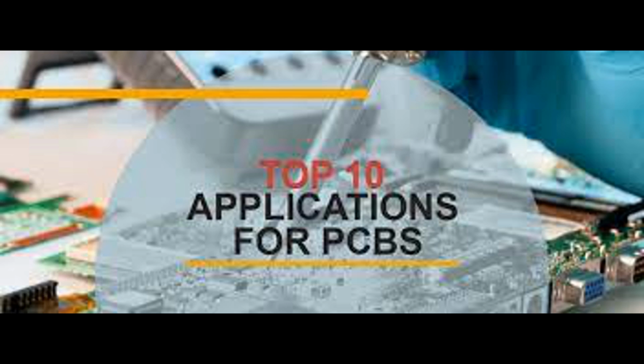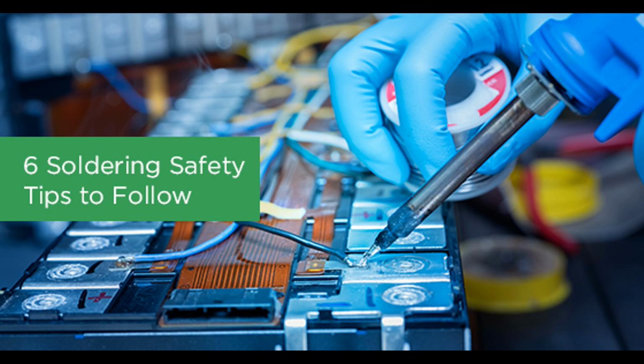The design and manufacturing of PCBs involve specialized software for schematic design and layout, followed by the fabrication process, which includes etching copper traces, drilling holes for vias, and applying protective layers. After fabrication, electronic components are soldered onto the PCB, and the entire assembly is integrated into electronic devices.